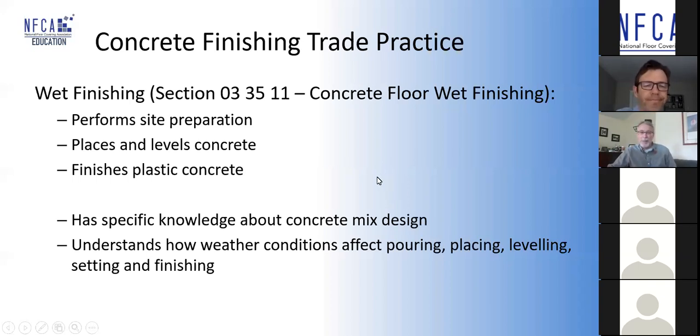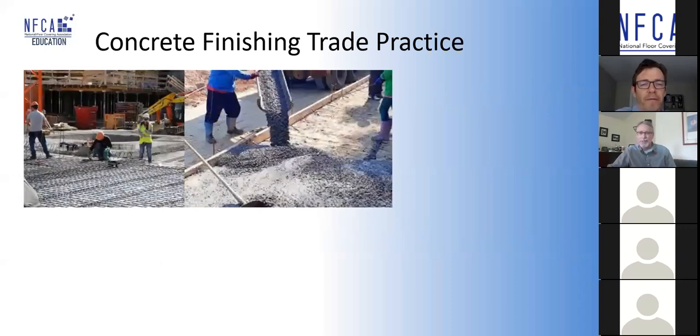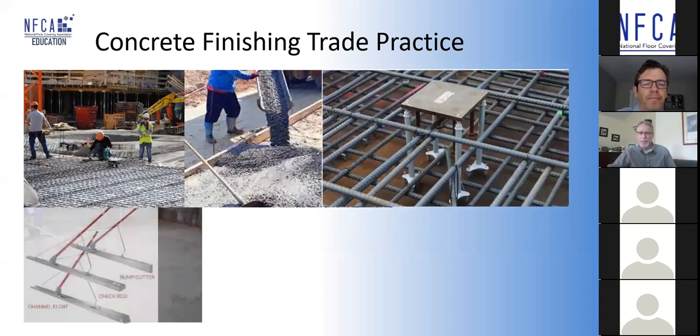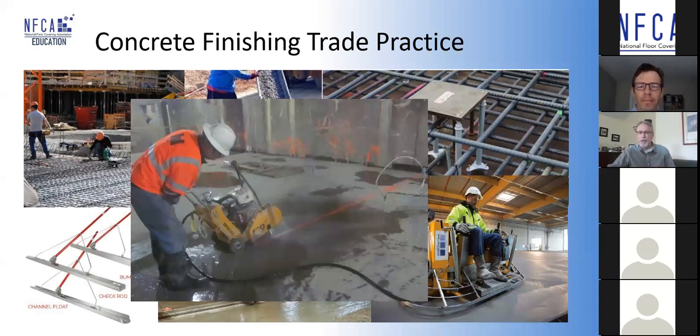So that comes back to just kind of a pictorial. Typically what we think of when we're finishing concrete. Wet finishing, exactly. So you see reinforcing steel that they've got to place around, they use tools, they use concrete floats. If there's any concrete people on the project, if you really want to make the flooring covering installers' lives happy, don't use a bull float, use a highway screed. Anything that we can do to cut off the high points in the concrete, the happier everybody will be later on as the project opens up.